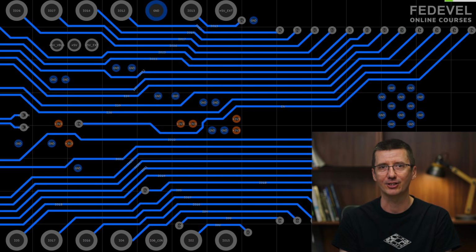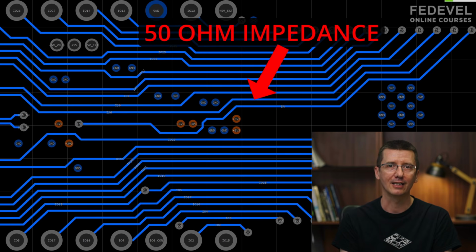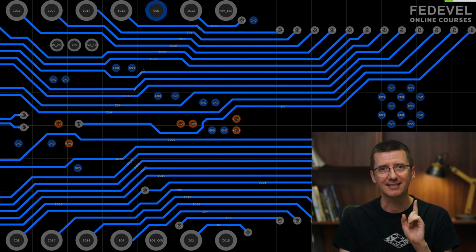So, how do we know what track width we should use? There are different types of tracks on PCB, but in most projects the most common ones are digital signal tracks. And usually these are routed with 50 ohm impedance. Notice, I didn't say mils or millimeters. I said impedance. So what's the track width for 50 ohms? Very good question. Here is a simple answer.